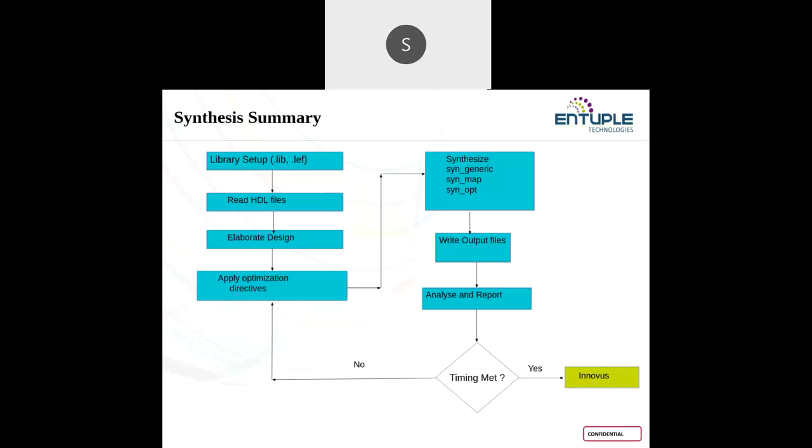I'm telling the tool to fix my timing violations incrementally. Usually, the path is related to a slack, and obviously the slack is going to be negative. I need to make that slack positive.